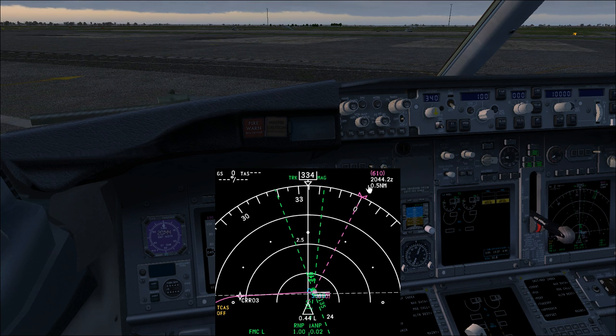Actually, as you can see, we have 2 dashed green lines that are the radials that we have selected for the actual VOR selection. I can rotate it, as you can see, from the course selector to any position I want. We have here a dashed white line that is the runway indication I selected, and the dashed line is the center line of the runway along the route.